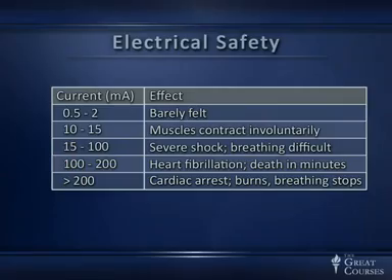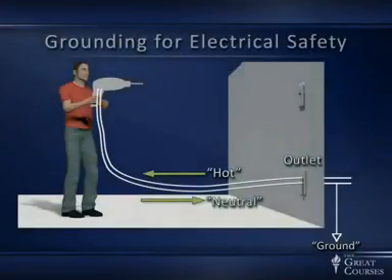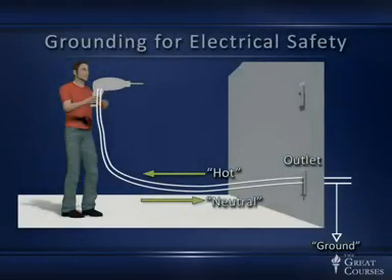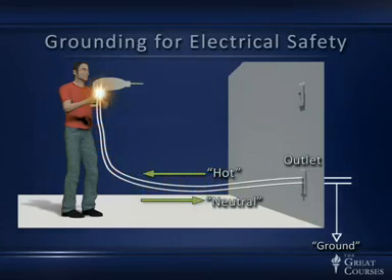So let's look a little bit more at electrical safety. We'd like to keep ourselves safe in the electrical context, and one thing we do is to use the fact that the earth ground provides us with a nice zero of potential, and one side of the electric power line is in fact grounded. So here I have a picture of somebody operating an electric drill with 2 wires supplying it from an outlet in the wall. And one side of that power line is, as I say, grounded. The other side is the so-called hot side. The grounded side is called neutral in electricians' parlance.